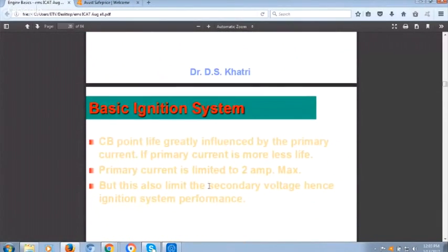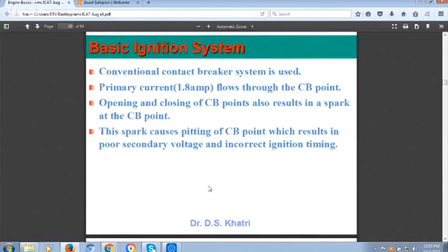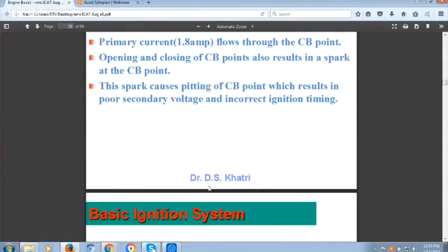Now we have discussed a little bit about the air-fuel ratio. Another important point was the ignition energy. Let me brief you about the ignition system also. Earlier, we used a contact breaker point. You know that the ignition energy required during the spark is around 20,000 to 30,000 volts. Because your battery source is 12 volts, that voltage is converted to 20,000 volts by an ignition coil, right?